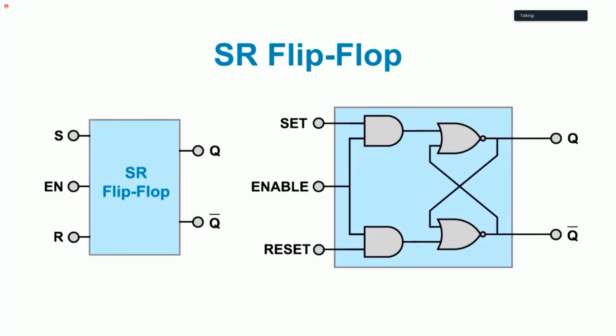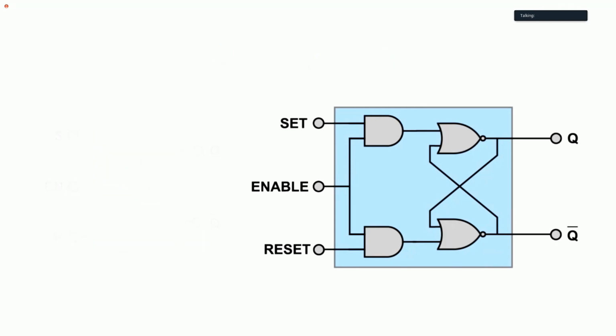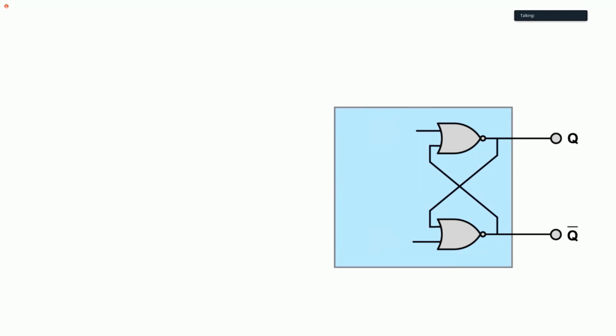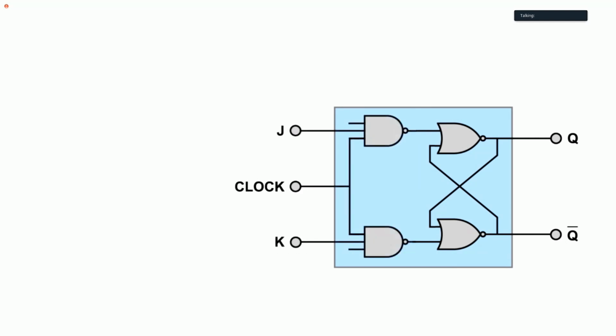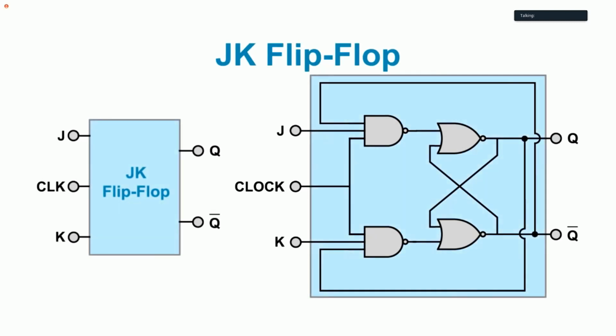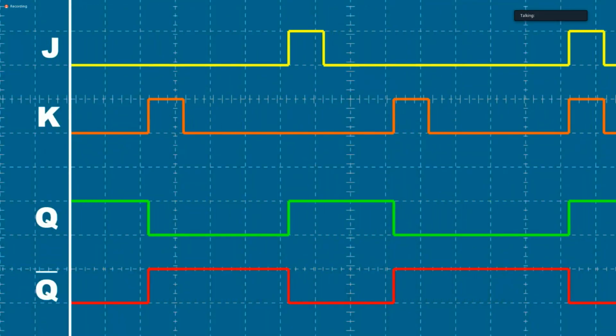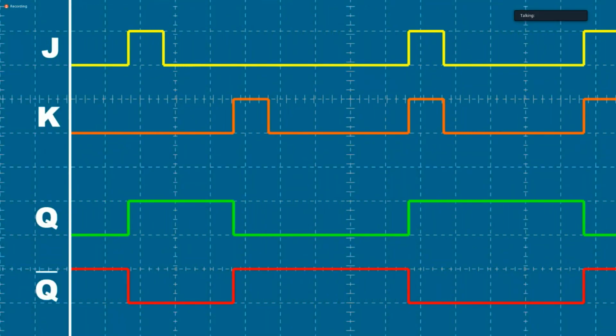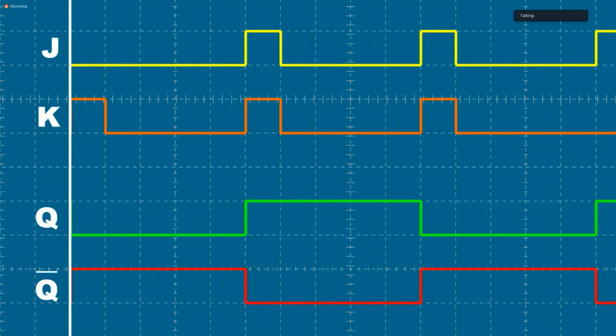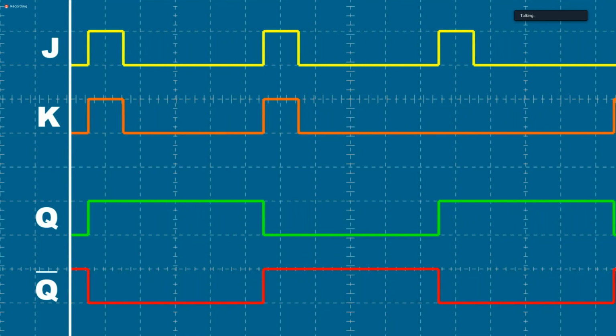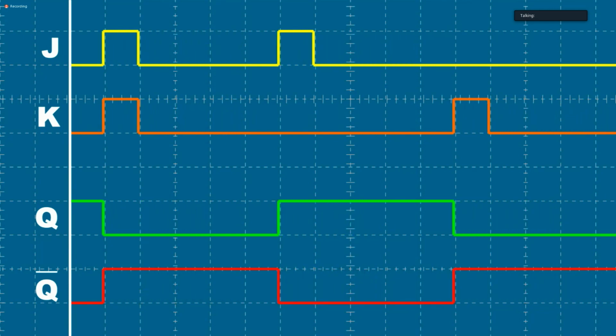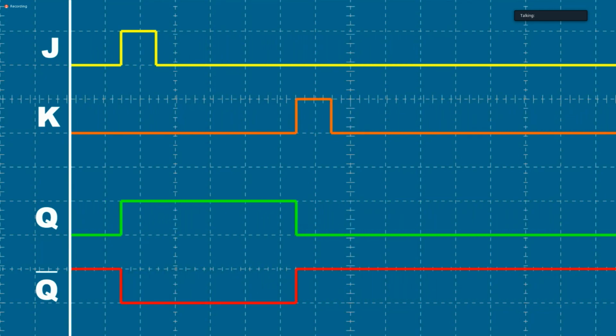But this is where JK flip-flops come in. Let's look back to our original model of a gated SR latch. In a JK flip-flop, the two 2-input AND gates are swapped out for two 3-input NAND gates. Having the third inputs of each NAND gate connected to the opposing outputs eliminates the invalid state. Inputs J and K still behave like set and reset, setting Q and then resetting Q. But if both J and K go active high, the outputs simply toggle. Boom, no invalid state. Problem solved.